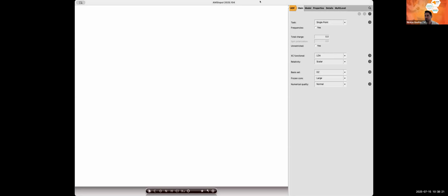So I want to run something during the tutorial, and I want it to be finished. So I'll just make a nanoribbon, and it's also interesting because you can vary many things. You can vary the width of your ribbon, you can vary the number of layers if you want, and you can see how Young's modulus changes. I'm just going to do uniaxial deformation, but you can see how this affects basically the mechanical properties of the material.